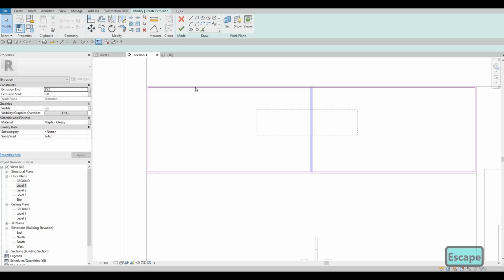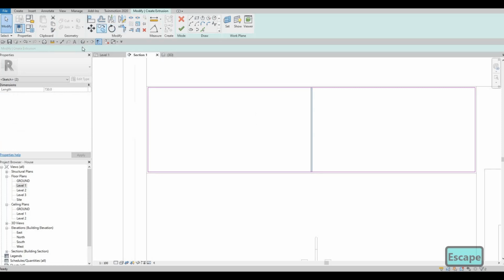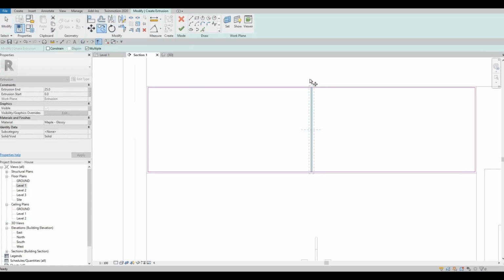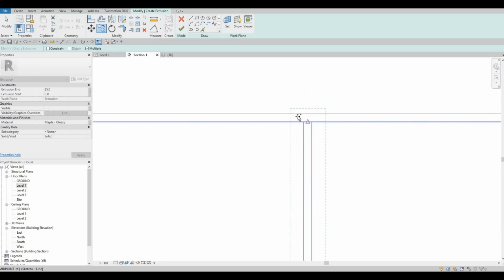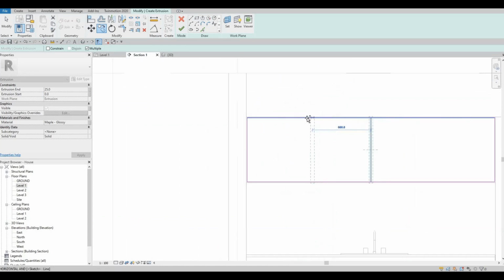And then after this, from here, I'm just going to copy this. So copy command CO, and then here we're just going to copy it in the middle of this. We could probably add, so here we have this width, so around 1400, and then the 1400 we can divide it by 3. So 1400 divided by 3, it's around 460.